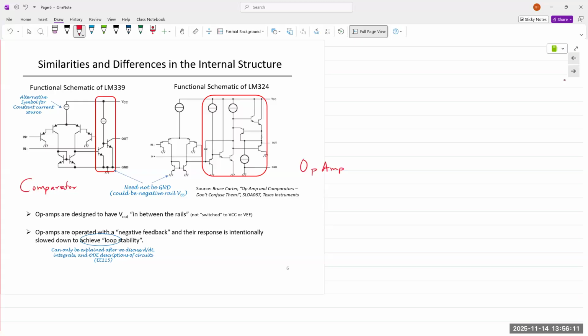It can perform a variety of mathematical operations like addition, summation, subtraction, difference, differentiation, integration, and then of course amplification. It's a very important component in electronic circuits. Okay. So again, for a comparator, the output goes either to plus VCC or minus VSS. So positive supply or the negative supply. So its output is kind of like a rectangular waveform.